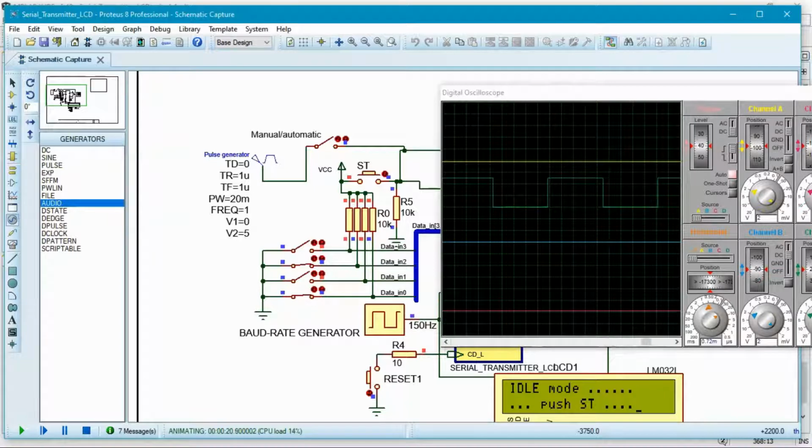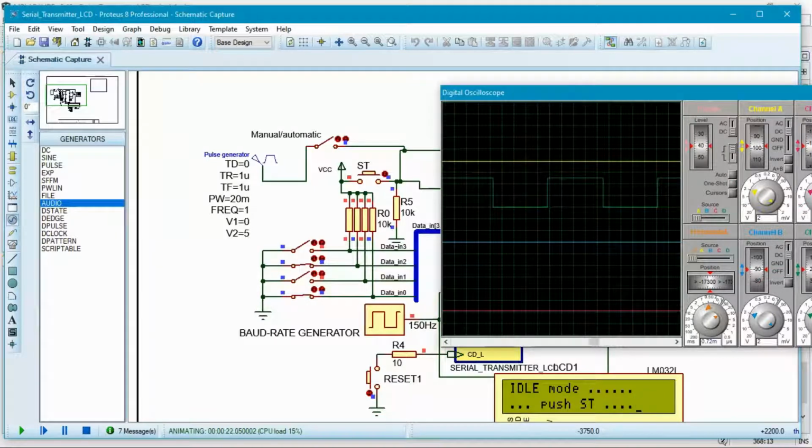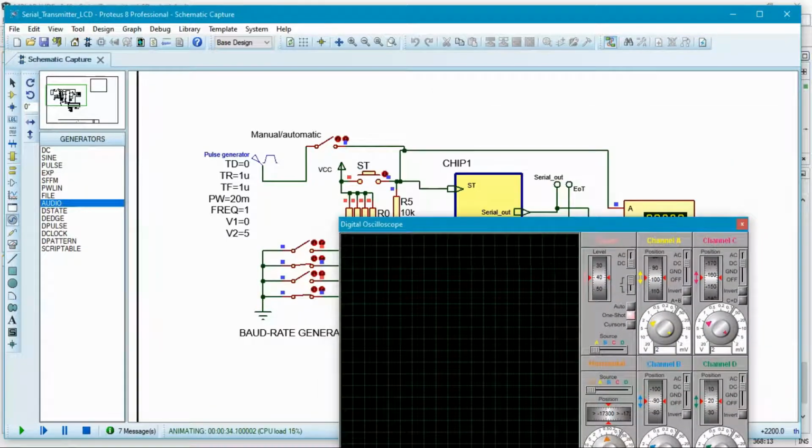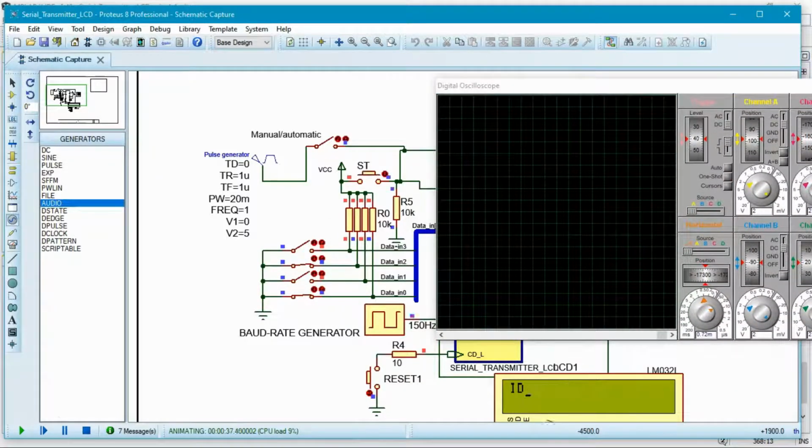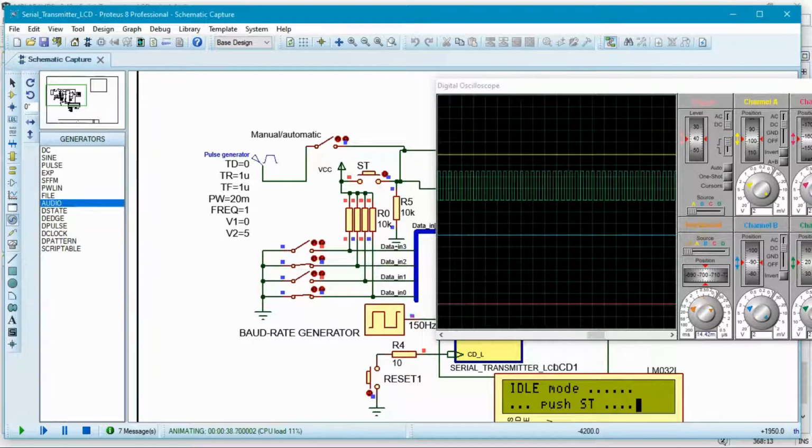So if you would like to capture the trigger that you are clicking with this start button, you simply select the one shot triggering function. You see, the source for this shot is source A, that is related to channel A, and channel A is connected to the start button. So now it's time for clicking the button and capturing the signal. Okay, like this. Very well.